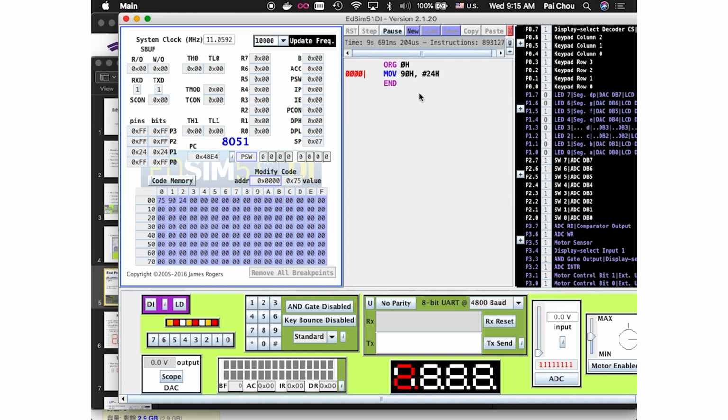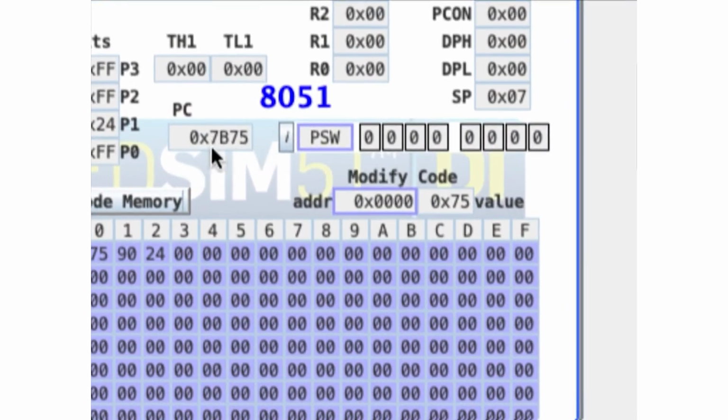And so that is just a single instruction. So okay, then what is it doing? You see PC is, well, this is not refreshing every single instruction. It's once every few hundred or a few thousand, so it's a snapshot, a sample point. It looks like it's cycling through the memory, right? And how many bits are there in this memory? There are 4 hex digits. So that makes it, how many bits? Not 64 bits, 64K of space.